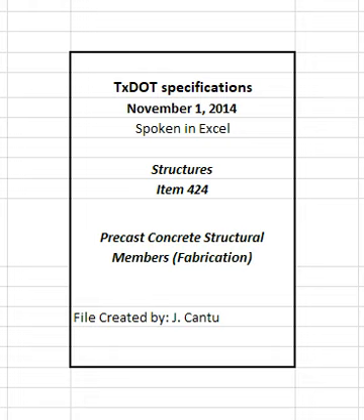4.2.5.3.2.3 Vibrating tables. Determine the size, number, and location of external vibrators to provide enough intensity of vibration to the desired area of the form. Adjust the spacing, frequency, amplitude, and duration of vibration according to the concrete mix and size of member to produce uniform consolidation of the concrete.